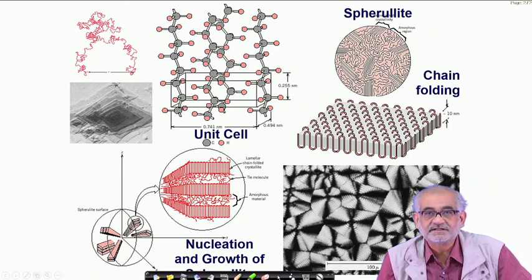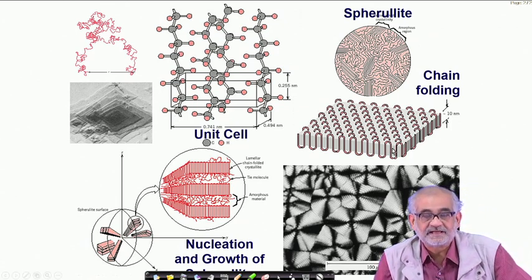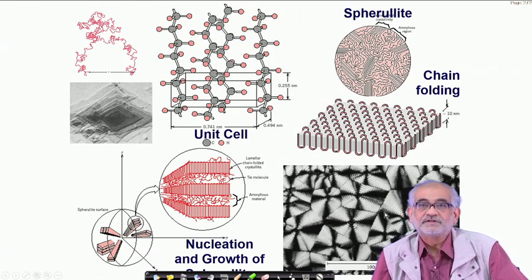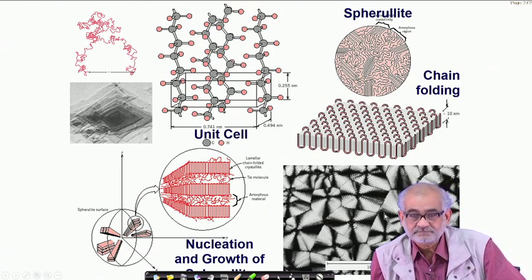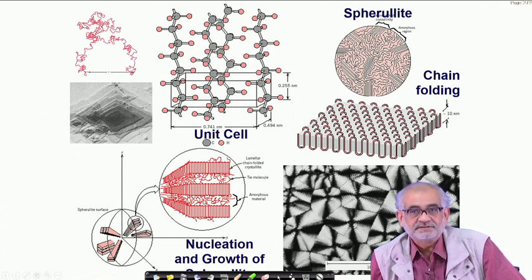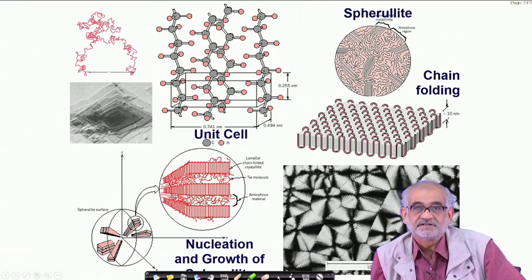And if this directionality continues in 1 dimension, 2 dimensions, and eventually even 3 dimensions, then we end up getting such a crystallite grown out of polymeric material. So the point I'm trying to make is that metals could be 99% or more crystalline with very little amount of crystalline defects, while certain types of ceramic materials, particularly the semiconductors or compound ceramics, can also manifest similar 99% crystallinity, or certainly more than 90% crystallinity.